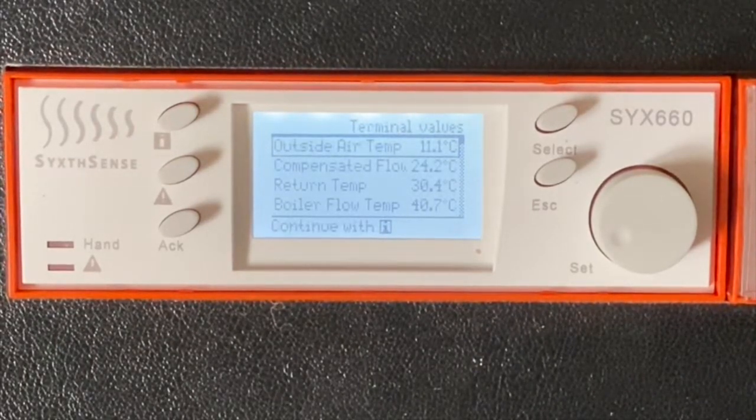For certain applications we need certain sensors connected, so just make sure that they're all wired in correctly. Some of the controller types do have polarity sensitive sensors, so on the SYX66x product the sensor connections are polarity sensitive, so you must observe the correct connection of the sensors. All the other controller types are not polarity sensitive, and it doesn't matter if they are incorrectly wired. There's no damage you can cause to the actual sensor inputs by wiring them the wrong way around.